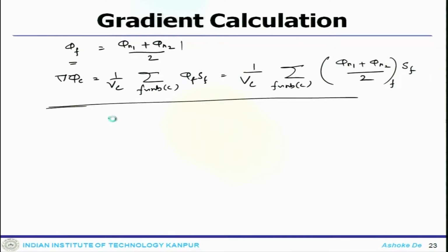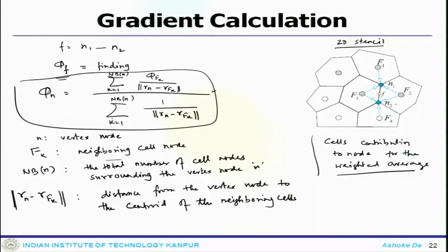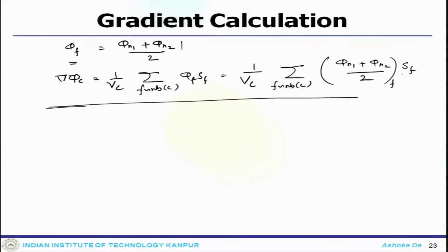If you look at this picture, it is possible that cells sitting on the wrong side can also contribute to this weighted average of the conserved variables. This can be overcome by using some sort of an upwind biased gradient, and the higher order calculation based on upwind biased gradients has memory overhead.